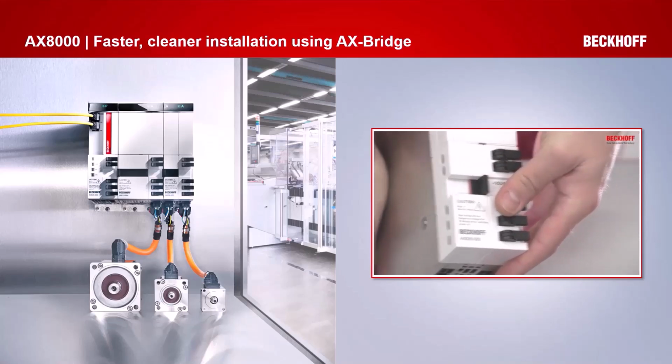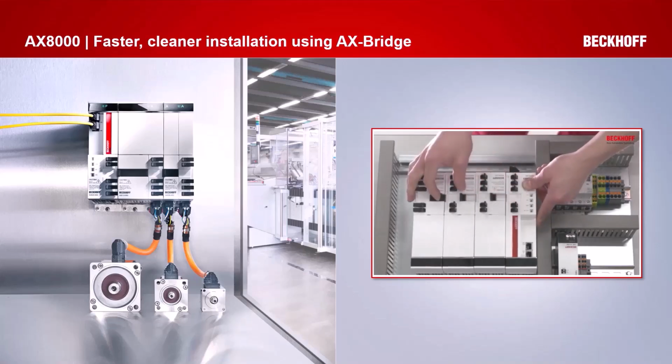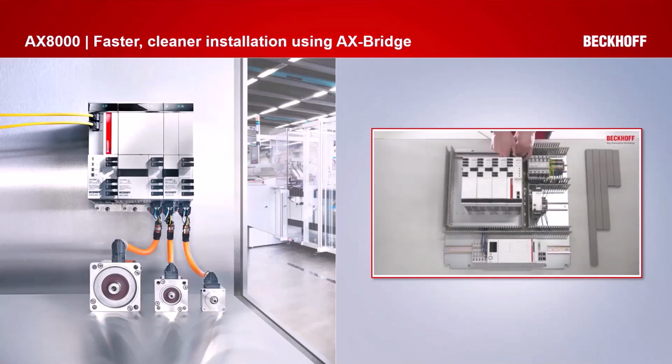It's really nice. It has some places where you can actually make it stay, which makes it very easy to install onto the system. You slide the bridge over, you connect the potential shield bar, you bring in the power connector, you bring in the field bus connector, and you're installed. So you can really see how clean and how easy it is to install there. And again, very, very simple, very, very compact, very, very easy to electrically protect.